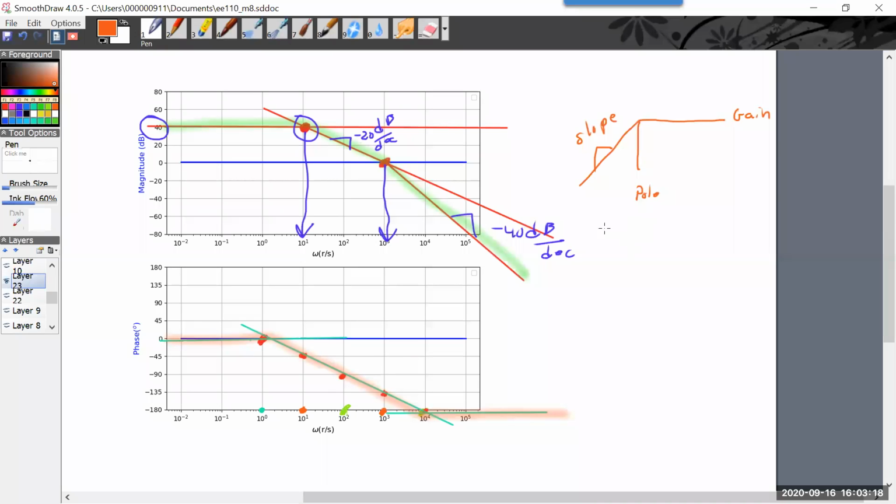And the phase would start off at, if it was second order, 180 down to 0, 90. This would be 40 dB up, right? And then if we had two separated poles, I'd have something sharp, something a little less sharp here, and then the